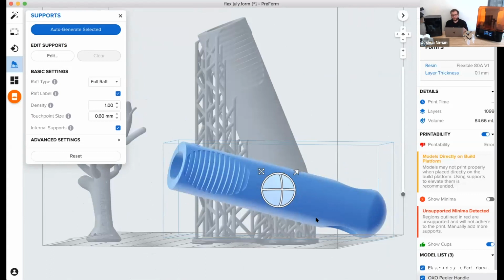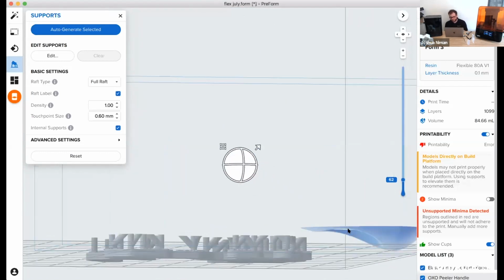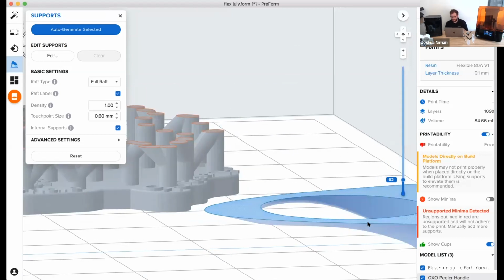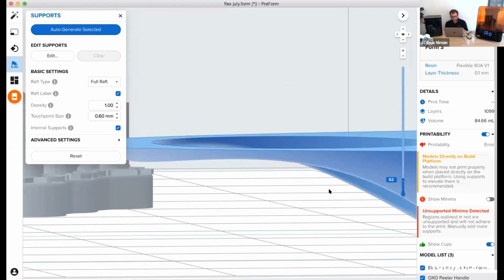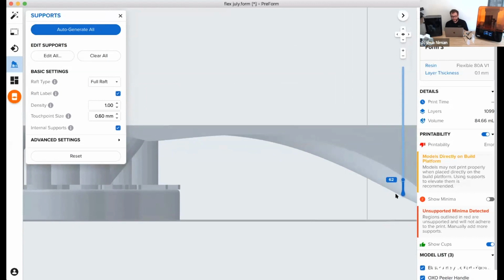Everything's trade-offs. People think they can 3D print, and it's like making something for nothing. It's like alchemy, but you don't get anything for free in this world. And so when we go really flat like this, remember these layers are a snapshot in time. This part exists at layer 62 looking like this. You end up with really fragile features that can easily have problems during printing.